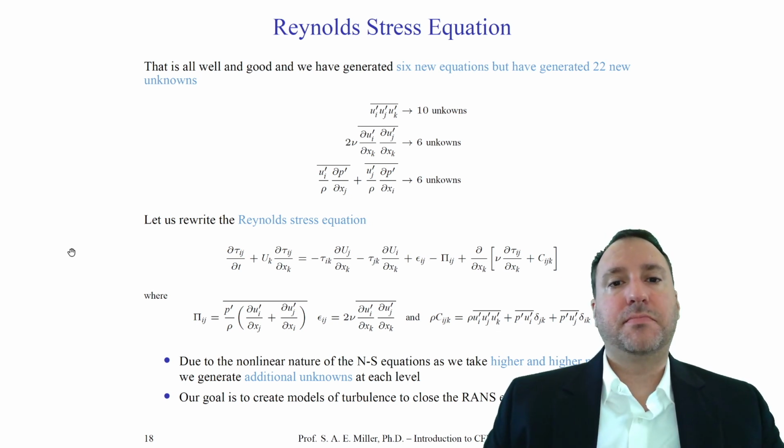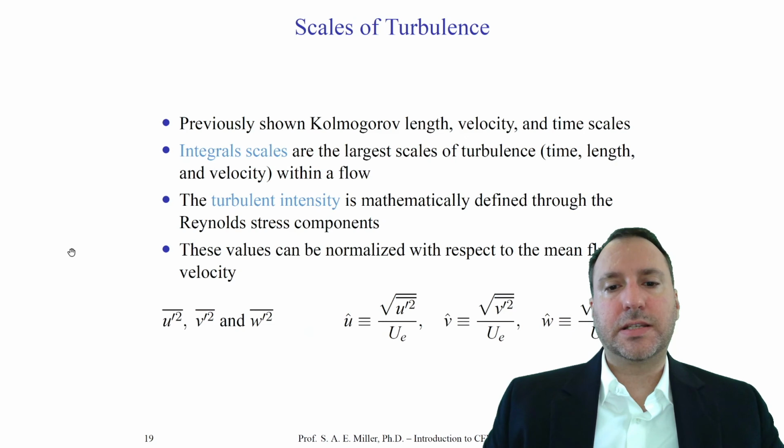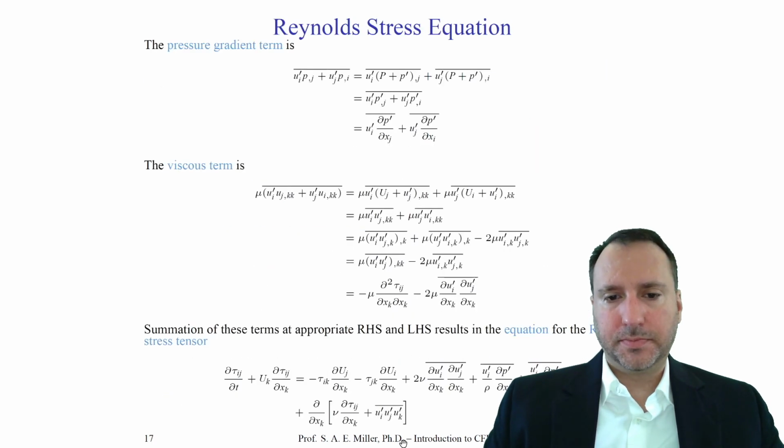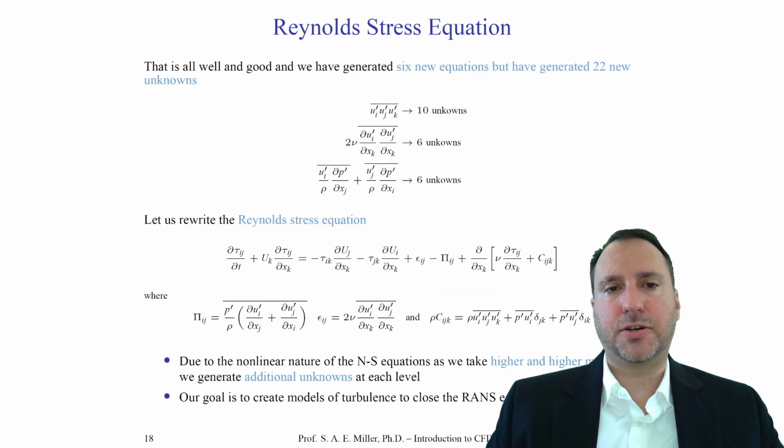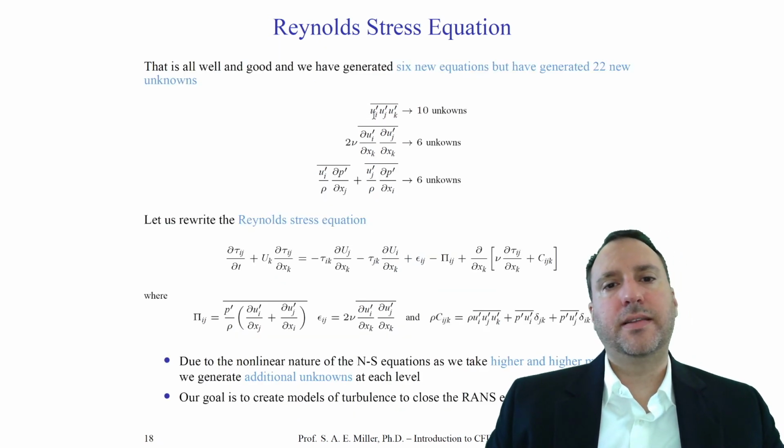And you might think that's a major victory, but oh wait. If you look in this particular equation, you'll see certain triplet averages, and also averages over partial derivatives of the velocities, and velocities with pressure. These represent new unknowns. So through this, taking the moments, and because of the symmetry of the stress tensor, we've generated 6 new equations.